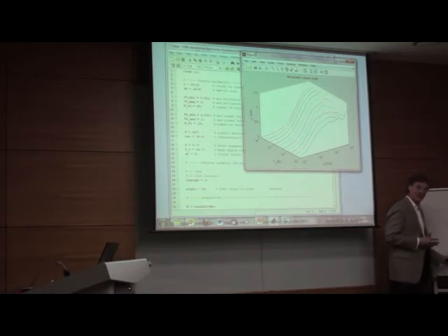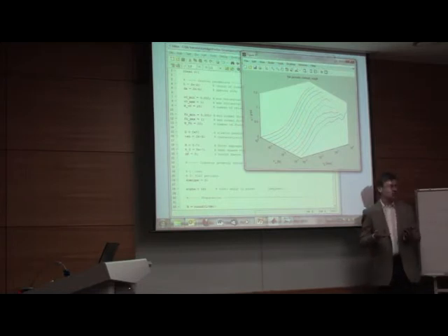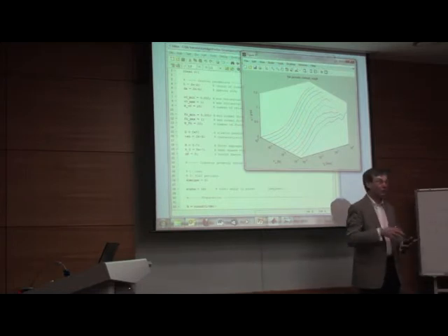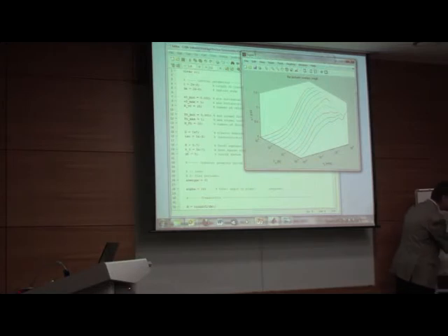So this is practically static friction. But if you move very slowly, then there is still no static friction. The real true static friction of rubber is small. What we see is kinetic friction at small velocities. And this part is practically this one. And I consider this one, and this part is in true rubber, but if you have the Kelvin model, then you have this part.